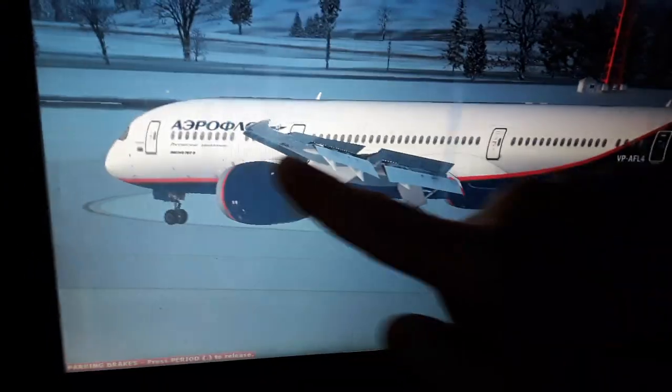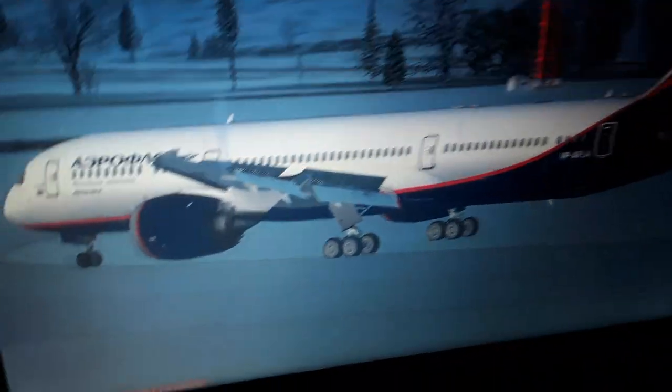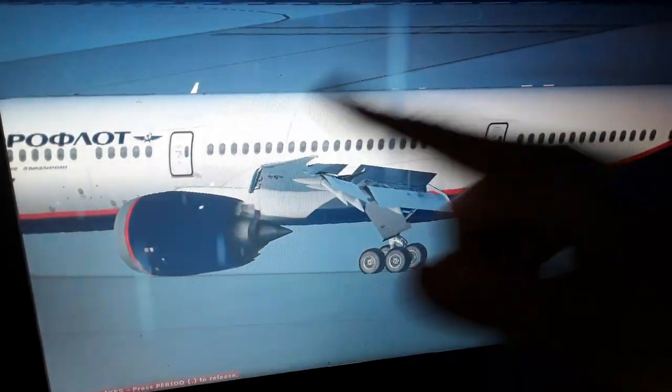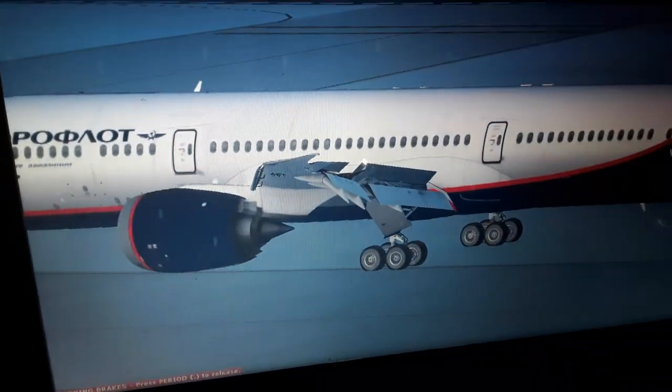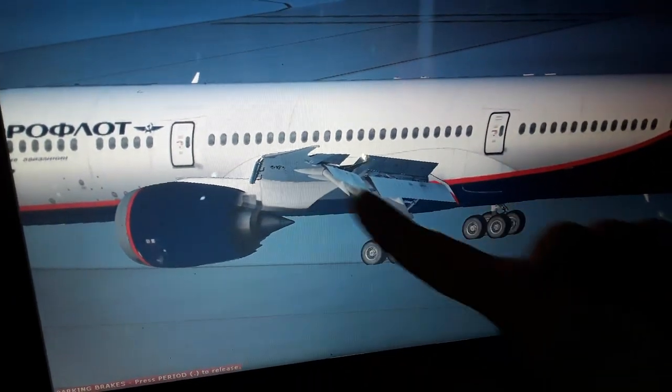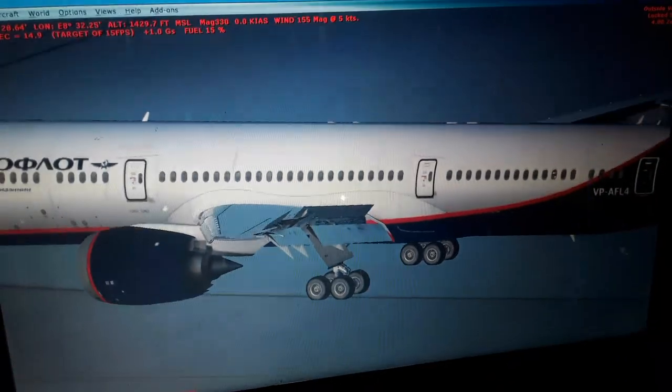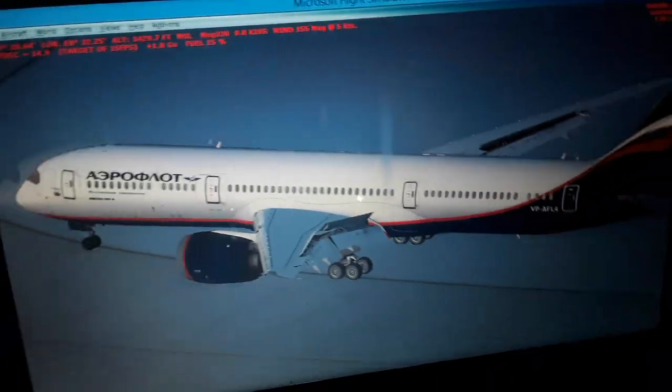Finishing the aerodynamics, you can see the bottom surface of the wings is more flat, and we also have the flaps extended, and in takeoff we're going to have a positive angle of attack. Using Bernoulli's principle, the airflow moves much slower below the wings, so we have higher pressure, which pushes the aircraft's weight and wings up into the air.